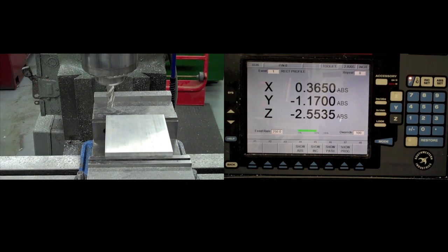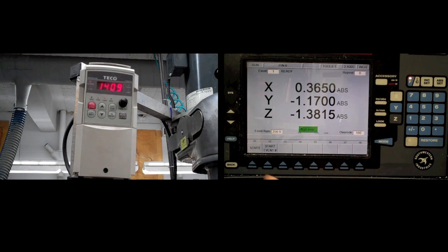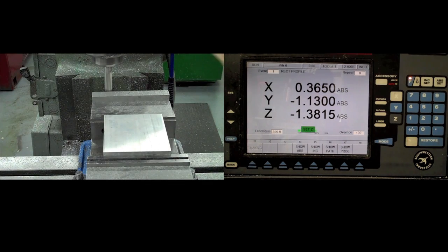Now it's time to machine the profile. Start the spindle and run the program. When prompted to, set Z. Plunge the mill into the part down to the correct depth. Press Go or tap the black button on the hand clicker.